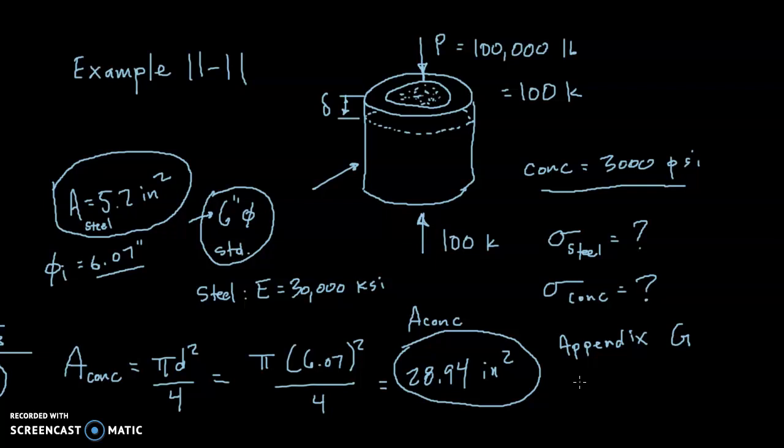One is 3,000 psi concrete, and the other is 4,000 psi concrete. You can tell that by looking at the ultimate strength column, where one is given as 3 ksi and the other as 4 ksi. So we want the 3 ksi concrete.